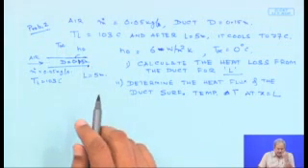And here we are assuming that the duct is of small thickness and high thermal conductivity. So, there is no conductive resistance. The temperature on the inside of the duct and the temperature on the outside of the duct are both equal. So, this is a very thin duct, and therefore, no conduction resistance. The first thing, the total heat loss from the air to the outside, can simply be obtained by making a heat balance. It's simply going to be m dot Cp delta T. So, we know the temperature at which it is entering.